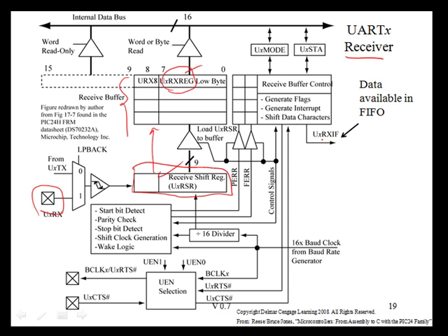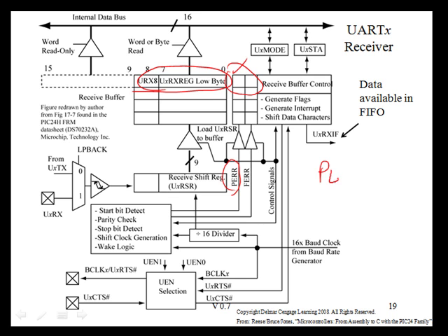This flag right here, the RX interrupt flag, will be set to a 1 if data is ready to be read from the RX FIFO. For each byte in the RX register FIFO, there are two accompanying status bits that indicate two different errors that can occur on a particular byte. One of the errors is called parity error, PERR, and if it's set to a 1, then it indicates that a parity error was detected for this byte.